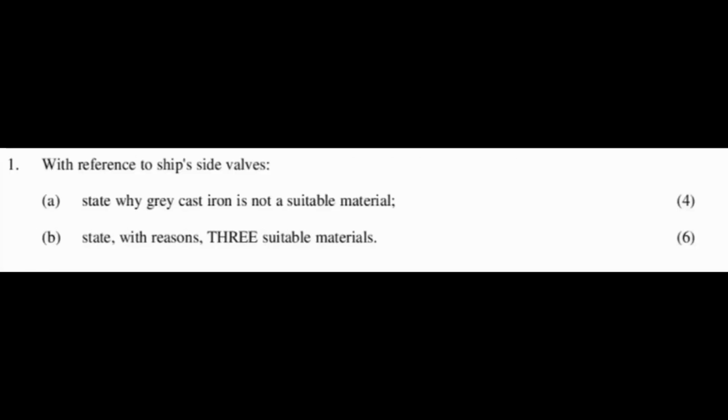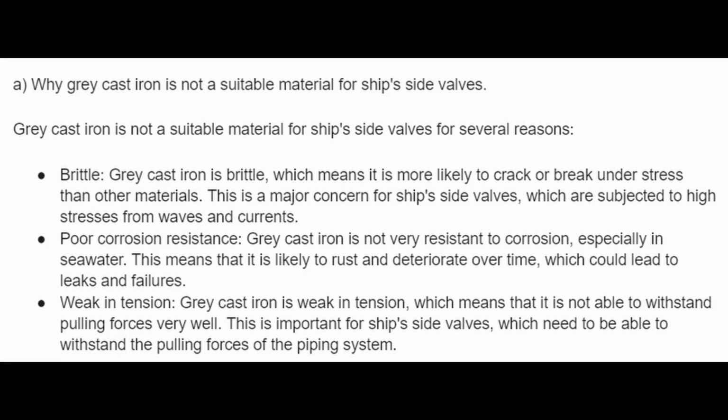With reference to ship's side valves. A. State why grey cast iron is not a suitable material. B. State with reasons 3 suitable materials. A. Why grey cast iron is not a suitable material for ship's side valves. Grey cast iron is not a suitable material for several reasons.